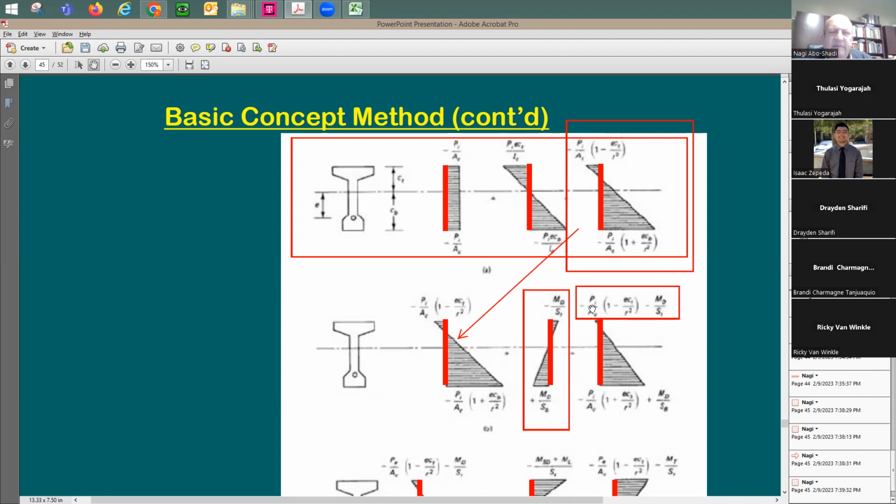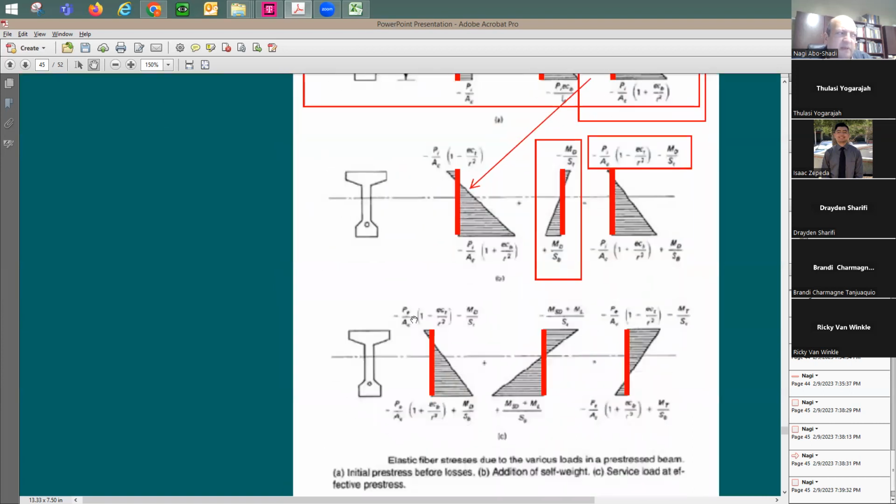So in this case, this is going to be PI, the initial pre-stressing. You still have lots of stresses locked in. Over time, you're going to be losing some of the stresses. So what happened to PI will become PE. So the stress here is going to drop down a little bit. Why? Because you're going to have some losses in the stresses, in the strengths.